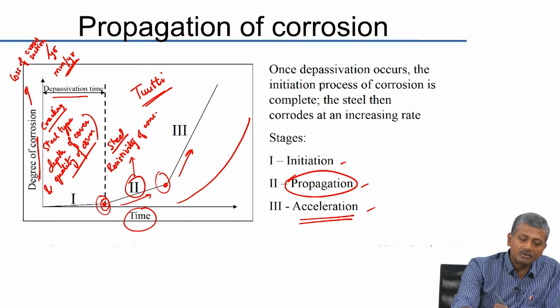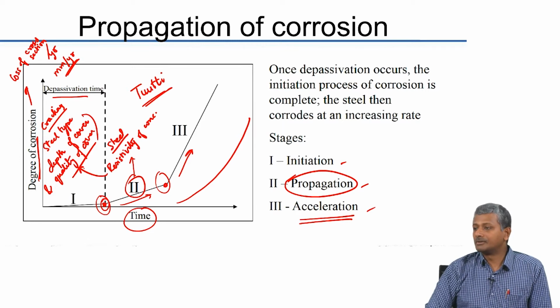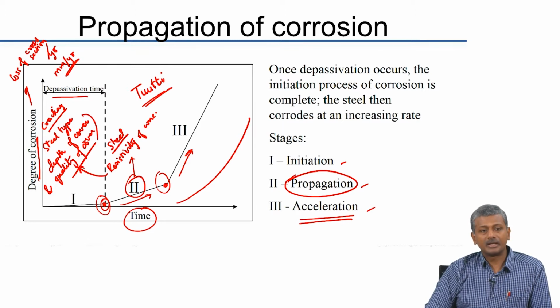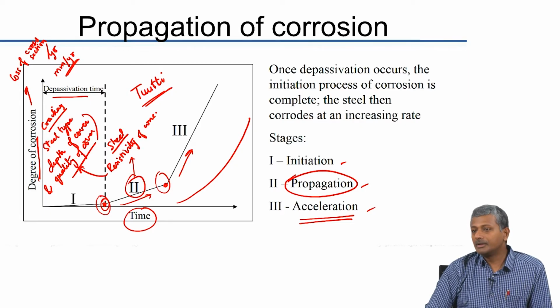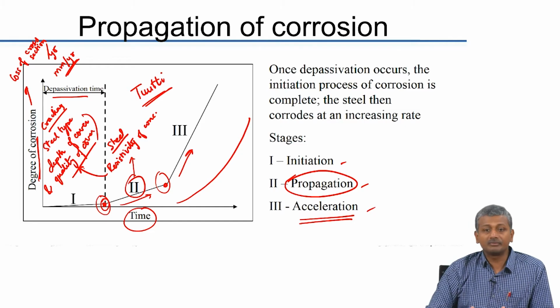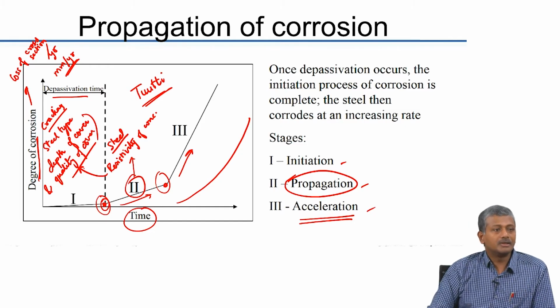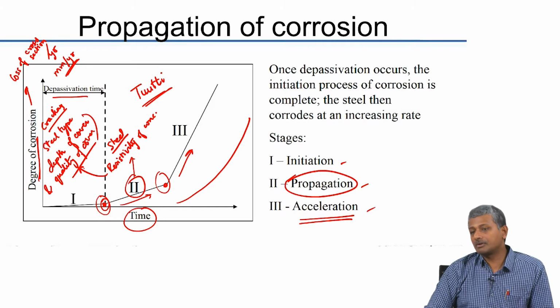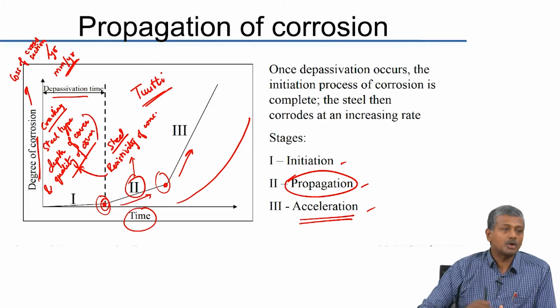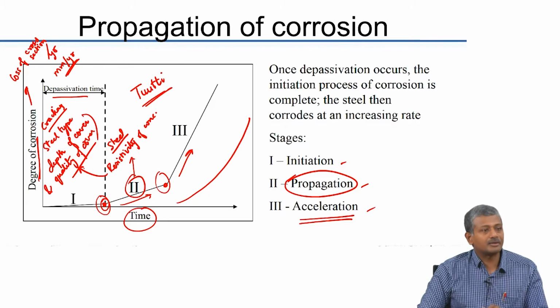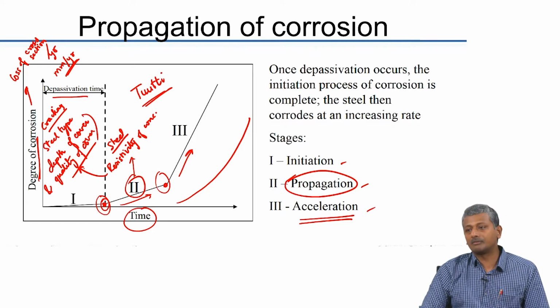Now this resistivity of concrete again is linked to the quality of the cover, right. Impermeability of the cover again determines the resistivity of the concrete. So the primary factor really that affects the rate of corrosion, whether initiation or propagation, is the quality of the cover concrete. And in most cases, the economically feasible solutions to prevent corrosion or to extend the period of corrosion to beyond the service life of your structure are related to improving the quality of the cover concrete.